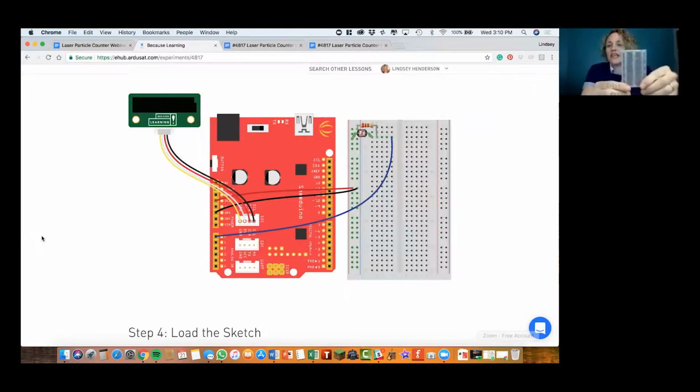It's important to understand how the breadboard's laid out before you start building. So if you notice, we have 2 rails on the side, kind of flappy. They come apart from the main breadboard. And these rails actually have a bunch of little holes. There are 2 columns of holes actually. And on the rails, the columns are connected. So anything you plug into a column will be in your circuit.